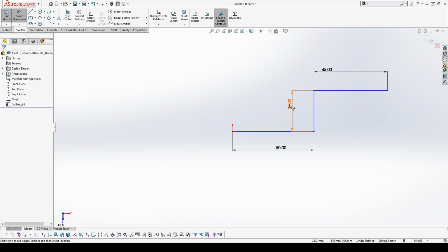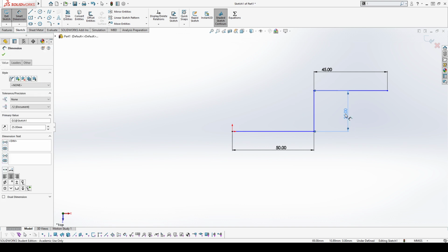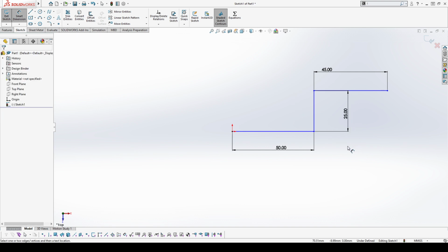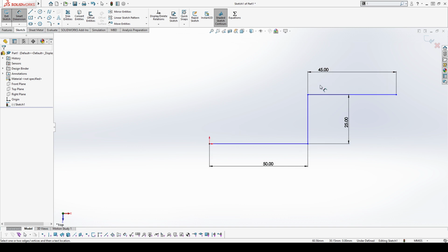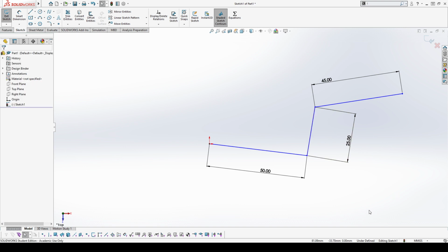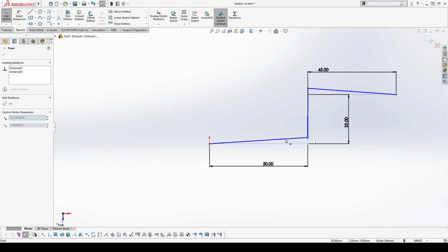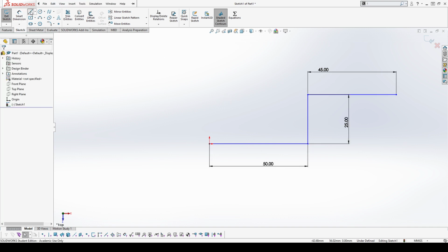All right, and for some reason my sketch isn't fully defined. I thought I drew everything in, and this line is horizontal, that line's vertical, that line's horizontal. What's going on? There's a couple ways to figure out what's wrong. One of them is to grab one of these points and just drag it, and you can realize that when I dragged those points, I didn't actually add in those relations. It just placed things in a way that looked horizontal. And if you remember, when I dragged that point, those little icons that popped up, they're in white. They're not in yellow like they were when we were actually drawing.